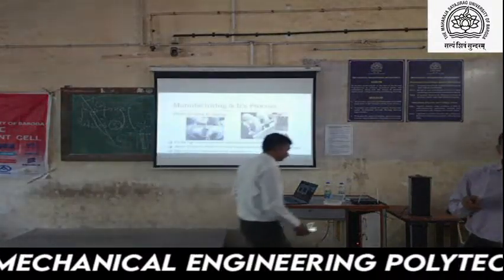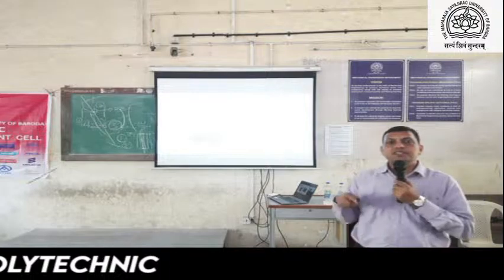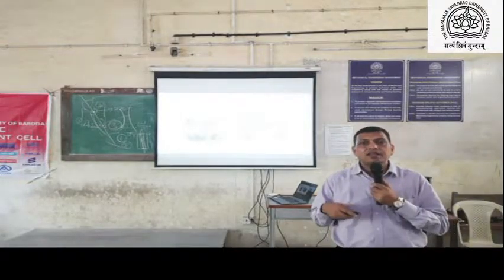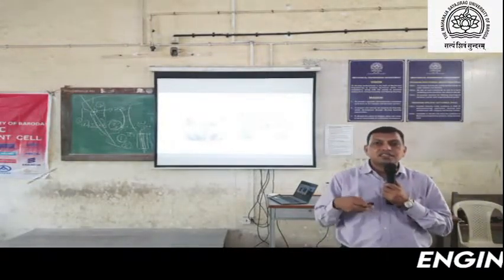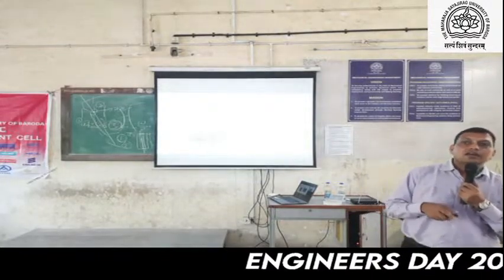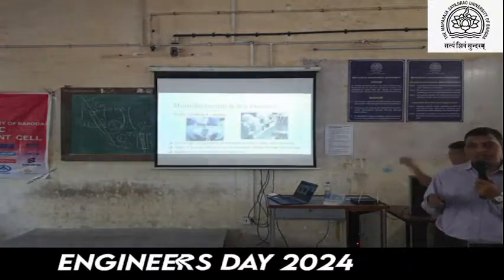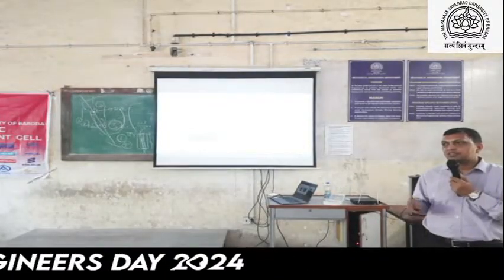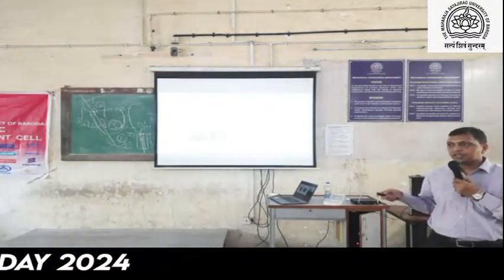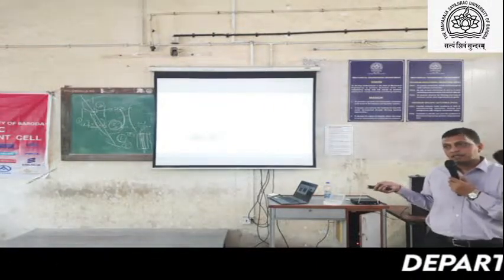Basically, grinding is to smoothen the surface. When the surface roughness is high, the gears generated are less accurate, and that will impact our operation. Grinding makes the operation smoother, reduces the vibrations, and gives good contact. So all these parameters we can maintain in the grinding operation.